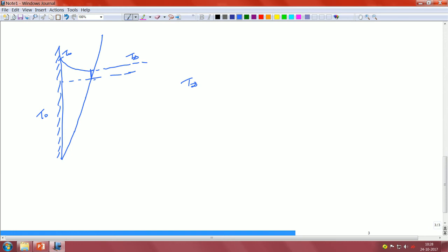And I will make a statement over here, as I said I am going to correct it in the subsequent presentations. What we can see over here, what will happen to the velocity? What is the velocity at the wall? Velocity at the wall should be 0, and outside the temperature boundary layer, I do not see why there should be any velocity, common sense, because the driving mechanism is gone. Temperature difference was the driving mechanism for the density. When the temperature equilibrates, that means there is no density change per se.